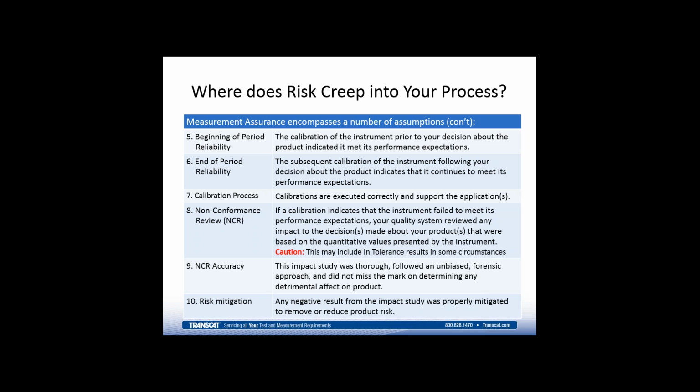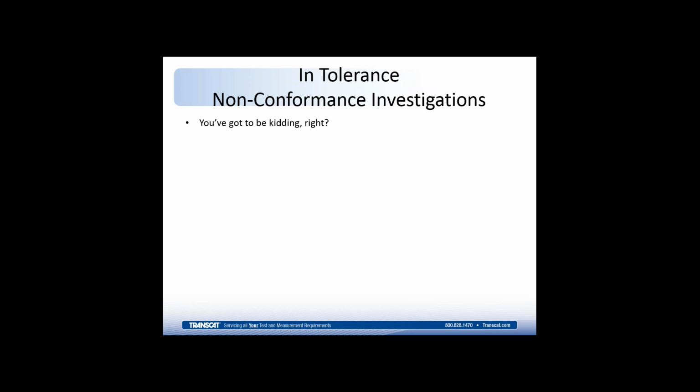We're going to take a look at the in-tolerance situation with low ratios where that can impact decisions about product. And when I say, hey, in-tolerance to non-conformance investigations to people, they say, you're kidding. I have to worry about an in-tolerance situation. I'm only looking at my certs to see when it says out of tolerance. Well, unfortunately, that's not the case if you have low ratios.